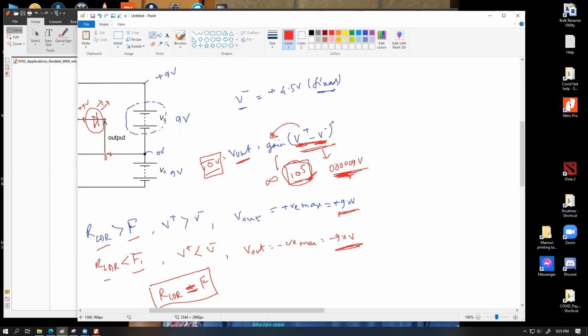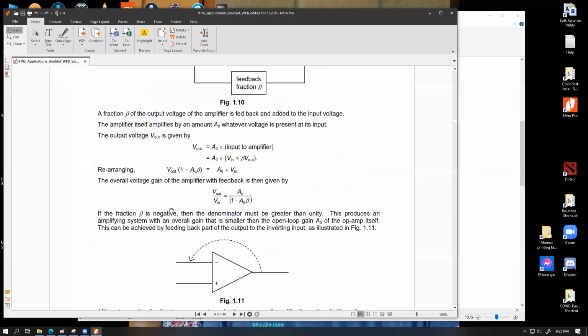Now, making this one small is not practical because this is an independent variable. This will be fed from the device that you're working with. So the only thing that we have left that we should be able to manipulate is this factor. So if we can somehow make this thing go down, then we can practically avoid the op-amp becoming saturated. So the whole purpose of this feedback mechanism, and to be honest, negative feedback, is to avoid saturation. So how does this work?